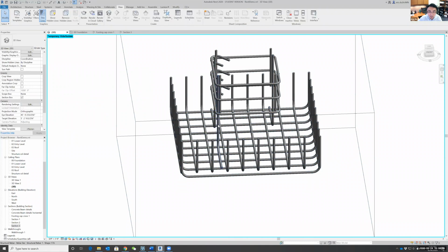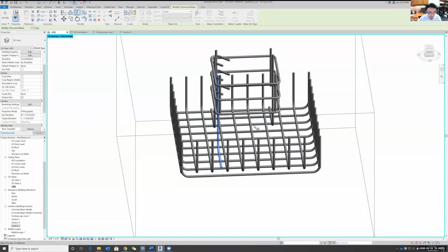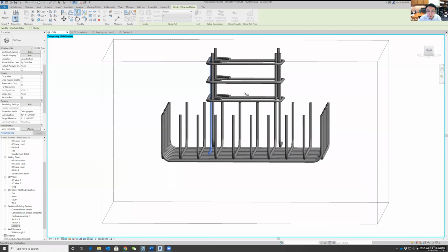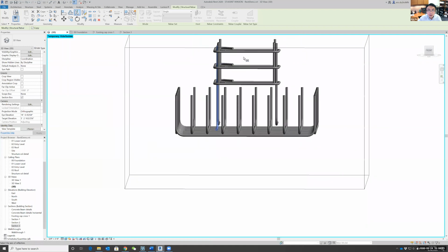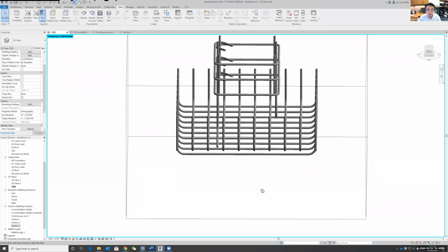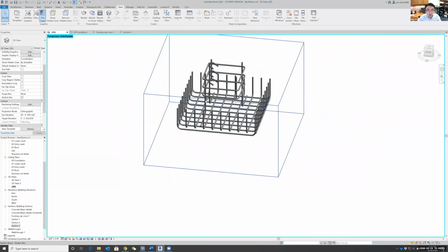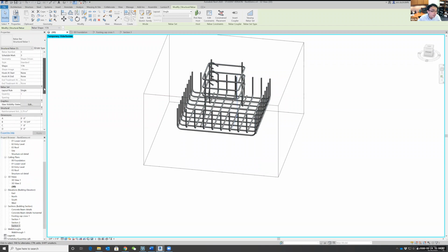I have them. Okay, so I also need to mirror this guy. So I can select in the 3D view, mirror, select the central line. Somewhere, oh, it's impossible for me to find the central line. Okay, so anyway, you get the sense, right? So we need to go to the red cross section of view and mirror that. Or another way to do that is just control button, and it's kind of like what you do dragging copies in a Word document. It's just control button and select this piece and go in that. And you can change the dimensions of the constraints later.